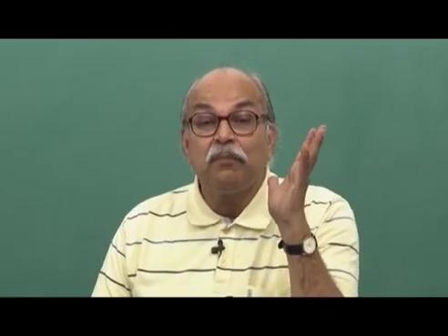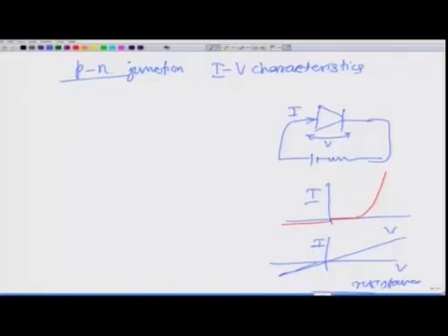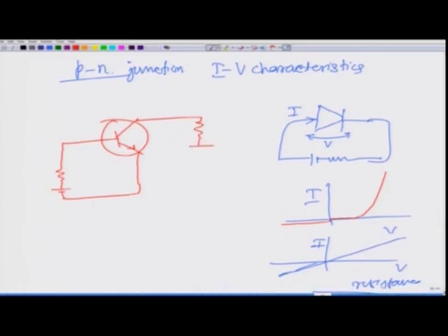Here I have two different parts, the input side and the output side. So, in the transistor circuit I can talk of various characteristics. Once again I am drawing this figure. Which transistor is this, NPN or PNP? From the arrow you should be able to answer these types of questions. So, this is the input side and the output side is like this. This is RL, this is RI, this is VBB and this is VCC.